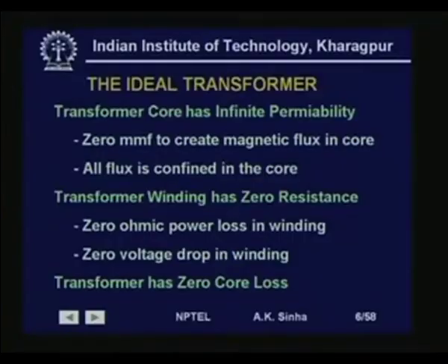Of course, we know these assumptions are not really valid. A physical transformer will have a finite permeability, it has a winding resistance, and it also has the core losses associated with it. But the concept of an ideal transformer provides us a very elegant concept for modeling the transformer.